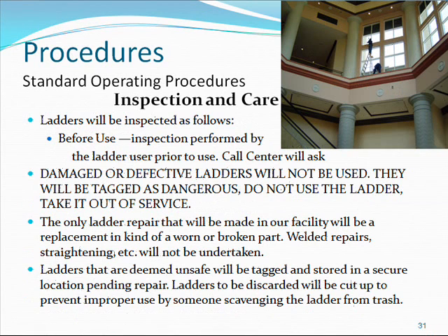Ladders will be inspected as follows. Before use, inspection will be performed by the ladder user. Damaged or defective ladders will not be used. They will be tagged as dangerous. Do not use the ladder. Take it out of service.